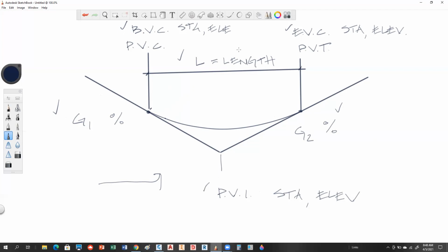And why you put it at a certain length, again, that gets into design characteristics. We're not going to worry about that. Okay, we're just going to pop them in there. So then what you're doing is calculating elevations along this parabola at a certain interval, like say every 25 feet or whatever. Okay. So the beauty is that this software does all of this for you. All you got to do is draw it, and it just pops those parabolas in. Any questions so far? No. Okay.